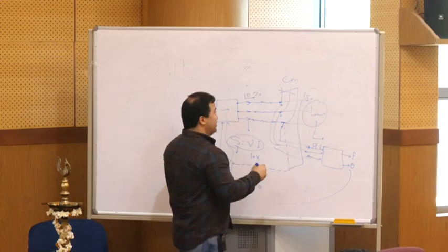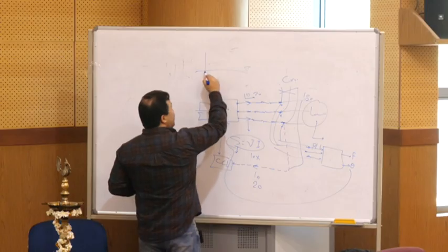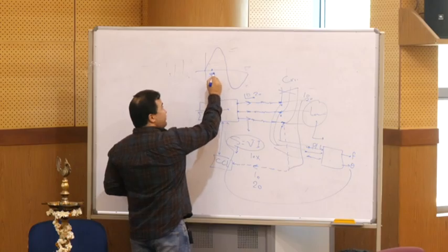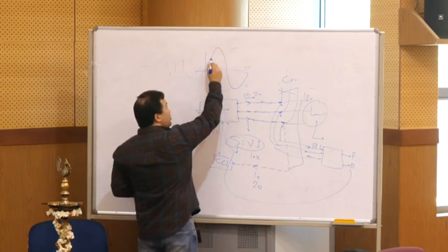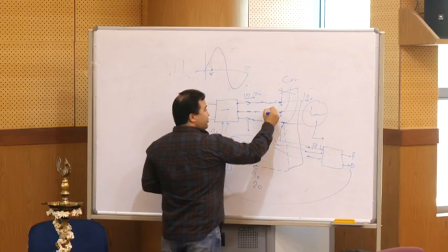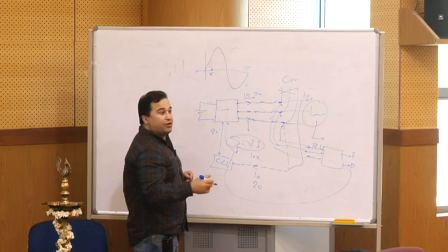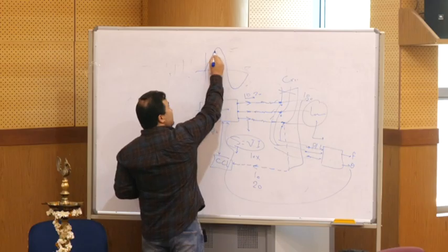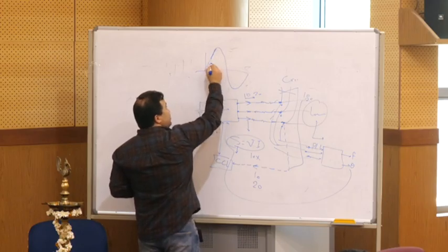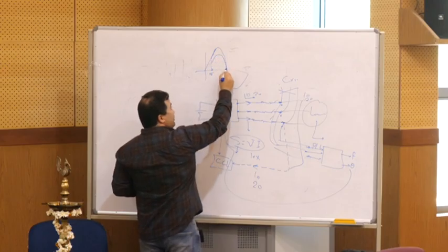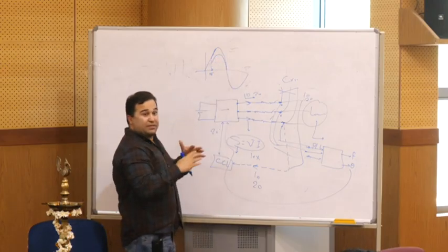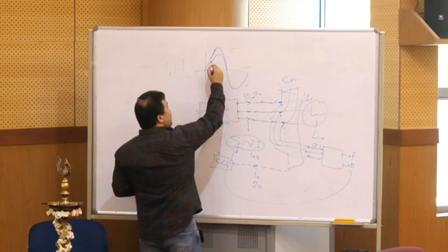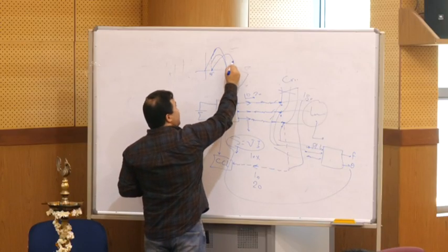So for example, if the grid current is like this, and at this time, 46 degrees, for example, you are going to integrate your converter. You connect your converter to the grid and inject 10 ampere. It should match with this degree. Otherwise, it makes some unbalanced situation, because then it is not matched.